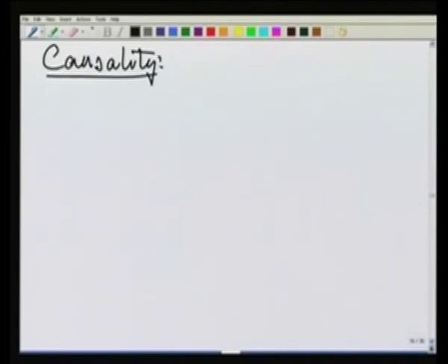If an LTI system is causal, then how does that manifest itself in the impulse response? This is an interesting question, and it has a very straightforward answer in terms of some of the results that we have stated, though not proved. Remember that the support of the output can be obtained in terms of the support of the input and the support of the impulse response.